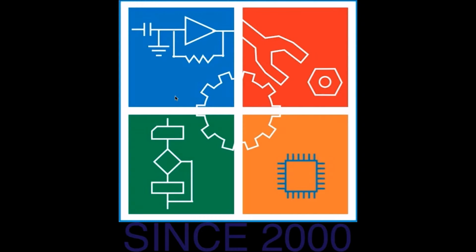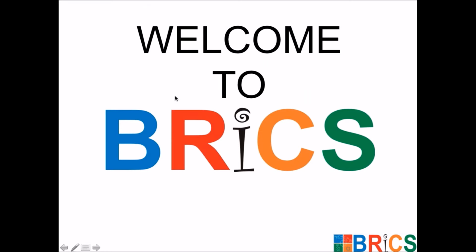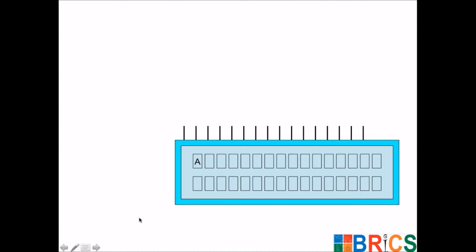My name is Rajiv and in this tutorial we are going to learn about the hardware detail of 16 cross 2 or 20 cross 4 LCD display. On this LCD display you will find that there are 16 pins which you can use to connect this display to any controller. Starting from this corner you will find pin number 1 and it will go up to pin number 16. Out of all these 16 pins, pin number 1 is called ground. This pin needs to be connected to the negative terminal of the power supply.